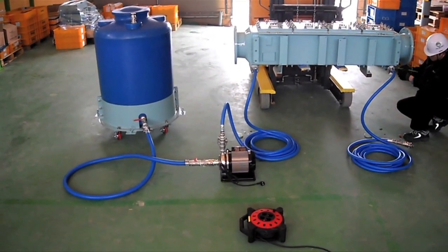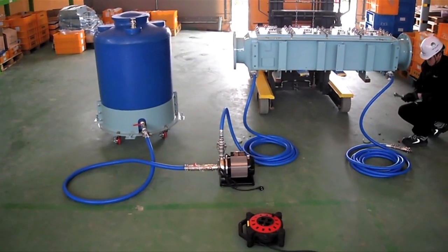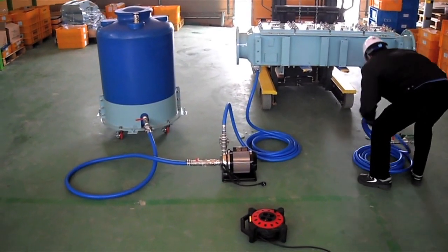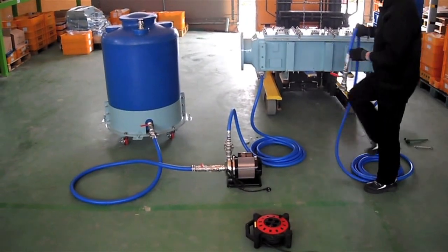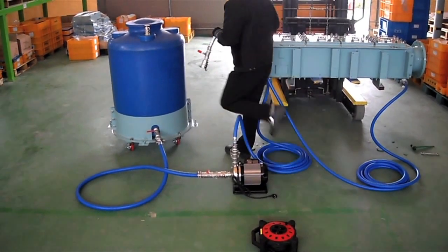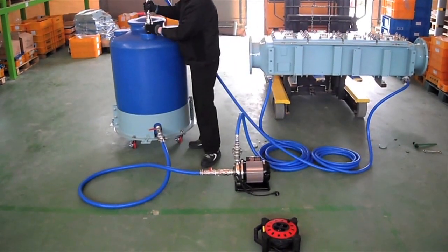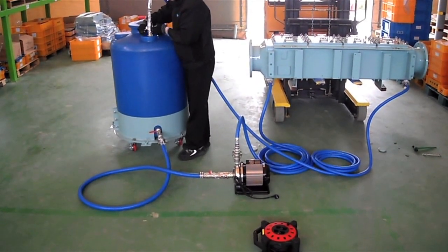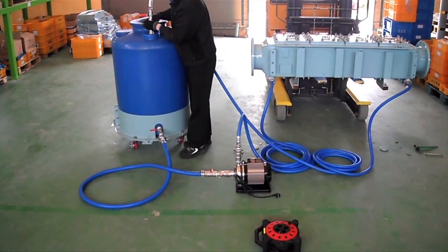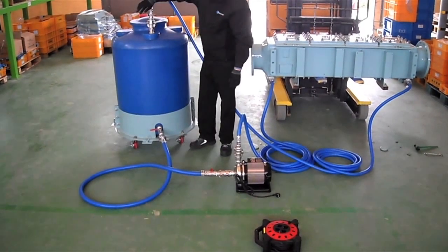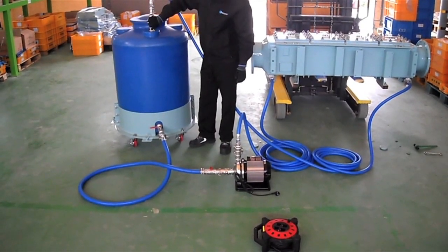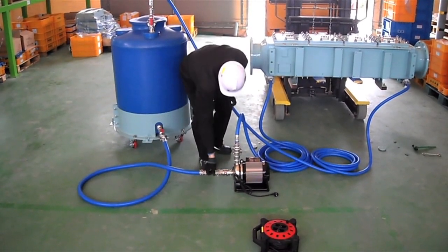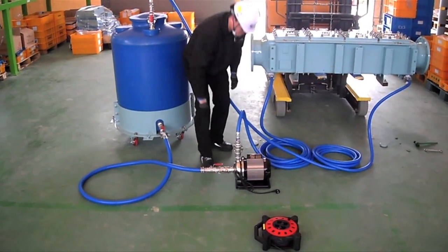Eight. Connecting ECU to tank. A. Connect flange F2 of pipe EC3 to drain D2 of ECU. B. Push tube detail A to the end as shown in section AA and in the picture below. C. Connect coupling C4 of pipe EC3 to tank T2.